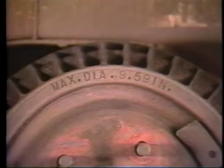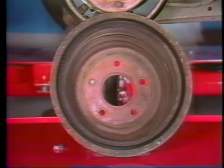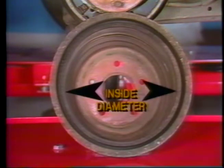Now don't forget, read the responses very carefully. At first glance, response B seems to be the correct answer, but the marking on the brake drum indicates the maximum inside, not outside, diameter of the brake drum after resurfacing. So the correct answer is response D.